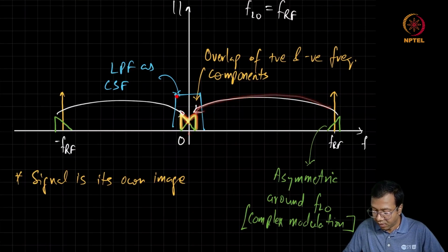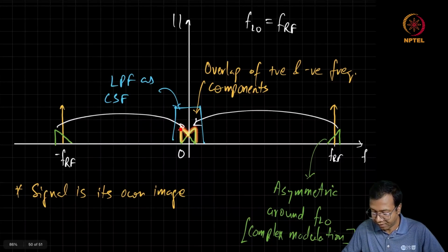So accordingly, the sampling frequency and the tracking bandwidth of the ADC need to handle only low frequency signals, and the channel select filter has become a simple low pass filter.